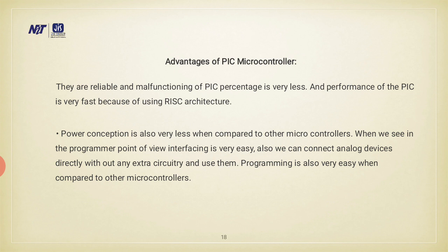A microprocessor system consists of data input, storage, processing and output devices under the control of a CPU. The main unit of a desktop PC is a modular system consisting of the motherboard, power supply and disk drives. The motherboard carries the microprocessor CPU, RAM, BIOS, ROM, bus controller and I/O interfaces. The CPU communicates with the main system chips via a shared set of address and data bus lines. The microcontroller device provides most of the features of a conventional microprocessor system on one chip.